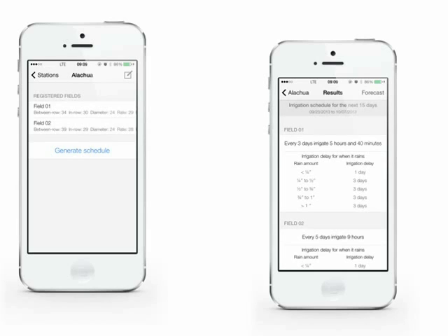If you have 1/4 to a half, it may be a 3-day delay, and the rest of these you can see are 3-day delays over a 1/4 of an inch of rain. The reason for that is 1/4 of an inch has filled that soil profile up to field capacity in this case. And so you would just wait for the next irrigation cycle.